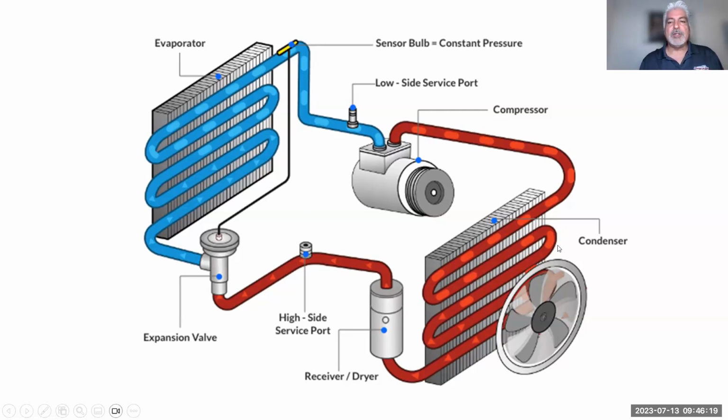Now, the other thing I want to get to is not all condensers are the same. Many guys are very frustrated by a vehicle not running as cold. In this case, what you can do is there are aftermarket condensers that have smaller passages and hold the refrigerant longer in the condenser because it's got so many passages. Because the longer you keep it in the condenser, the more airflow is going to go across it, the more heat you're going to release. So you can modify them if need be, especially on specialty vehicles or whatever you might encounter.